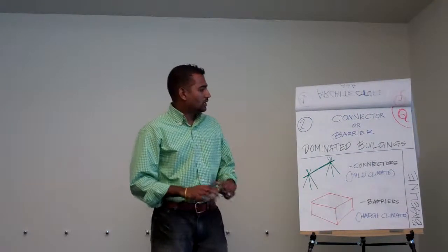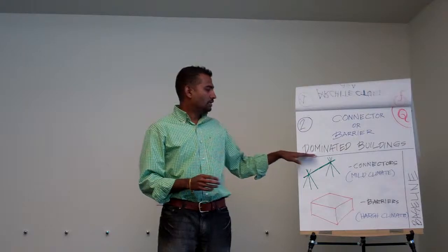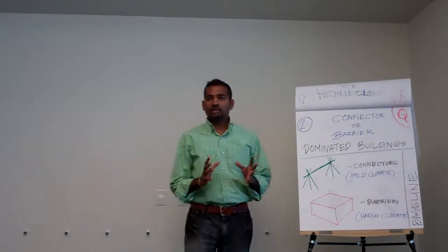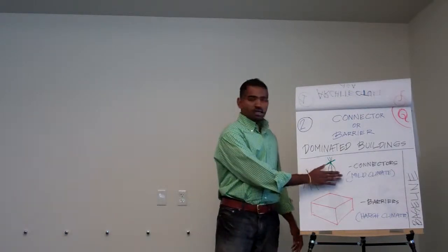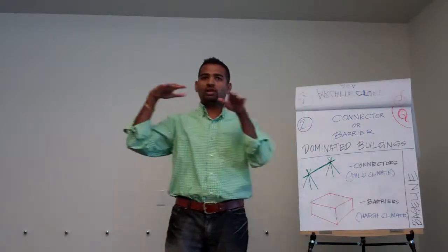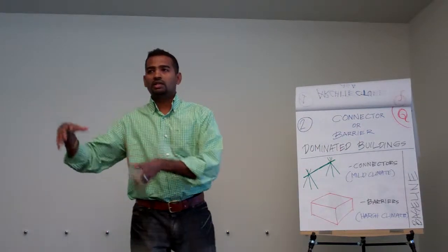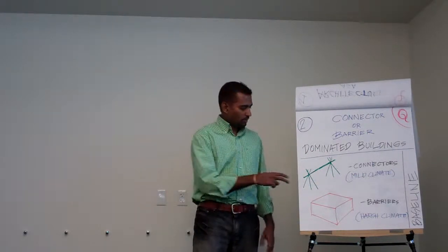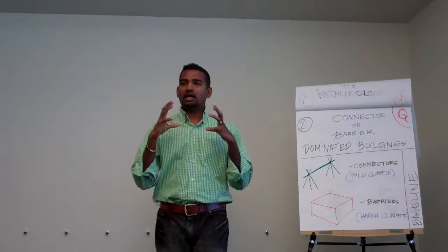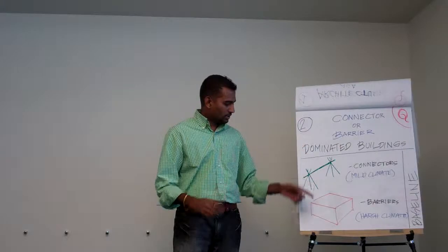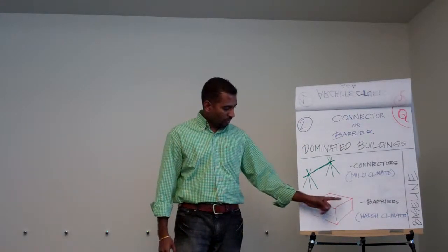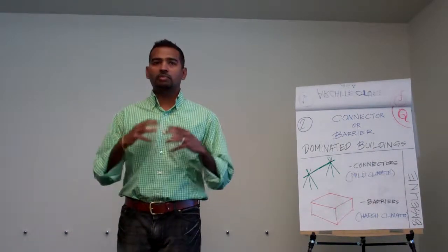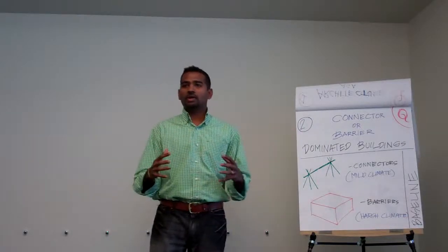Okay. Second question. Do you want a connector-dominated building or do you want a barrier-dominated building? That depends on the climate to some extent, right? If it is a milder climate, when the outside temperature is relatively closer to the inside temperature, then you want an open connector, a connector type building in concept. So it's very important to ask these two questions. And I'll tell you why. Before I get into that, for a harsh climate, what's the best response to a harsh climate? Be a barrier. You want a barrier building, right?